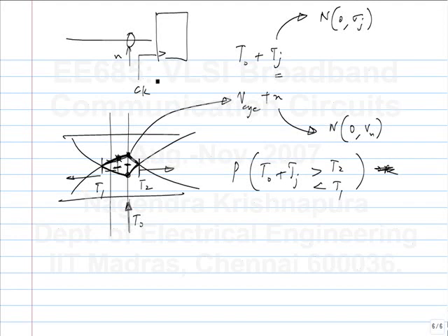So the received clock jitter is not included in this eye diagram. So far, the eye diagram that I have been plotting is before you add the noise and before you sample the signal at the receiver.